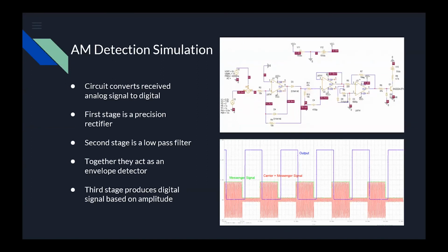This is a method that we've been using to test all of our components. We use two different sinusoidal bursts and multiply them using different methods. But in this schematic, we use multiplication to combine them to get a fully modulated wave that simulates what the receiver will be getting and feeding to the AM detection. I understand. Your sine waves are already chopped. They're already in an on-off mode, yes, and you just synchronize the two.